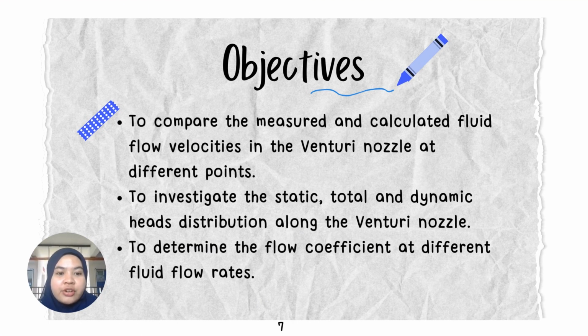The objectives of our experiment are, first, to compare the measured and calculated fluid flow velocities in the venturi nozzle at different points. Second, to investigate the static, total, and dynamic head distribution along the venturi nozzle. Last, to determine the flow coefficient at different fluid flow rates.